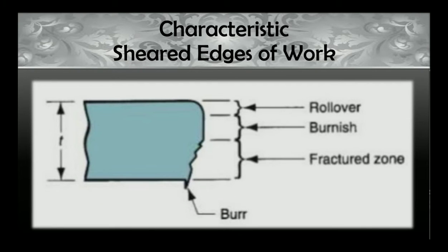So these are the characteristics of sheared edges of work. We have the rollover, the burnish, the fracture zone, and the burr.